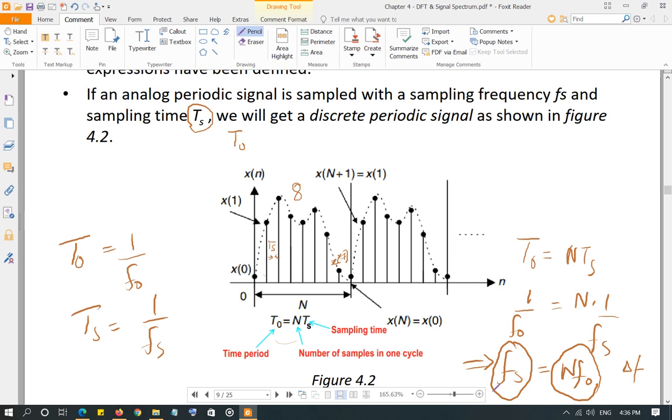Frequency resolution represents how small the frequency scale is in the frequency domain. The smaller the scale, the better you will be able to see the components. You will not miss any frequency component if the scale is very small. It's not going to introduce any new frequency in the signal, but it's just going to fine tune the resolution of the frequency scale.